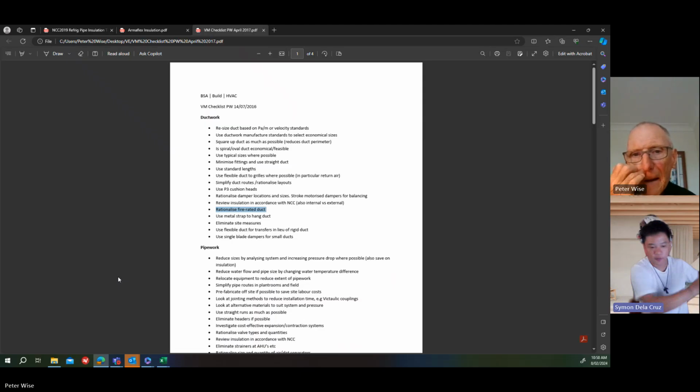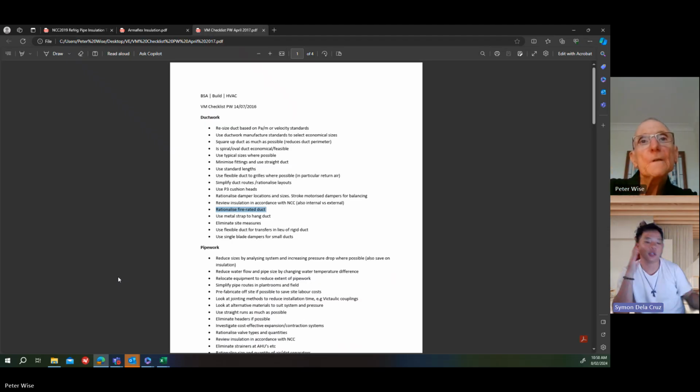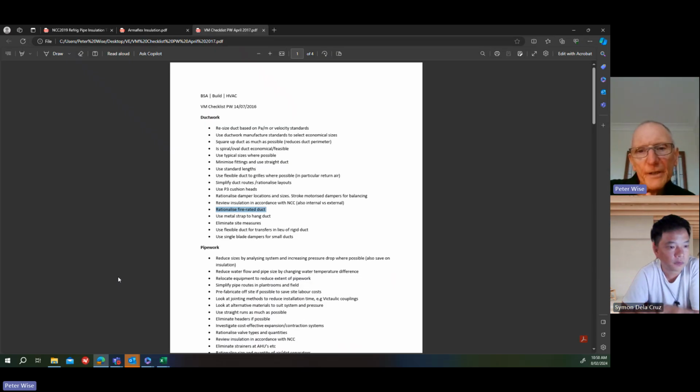Are they going to spray it first before they install, or install it first and spray? They have to install it first, because it's got to be a continuous spray. They can't have joints in the ductwork and then have to join them with the spray on it. So the ductwork is all finished to a certain point, and then they spray the whole section of duct.